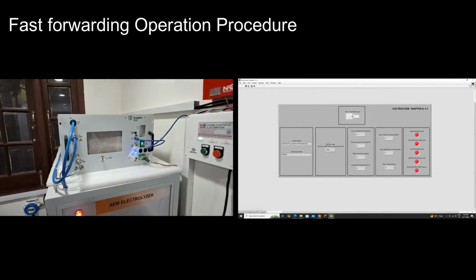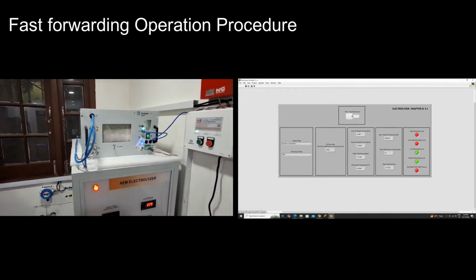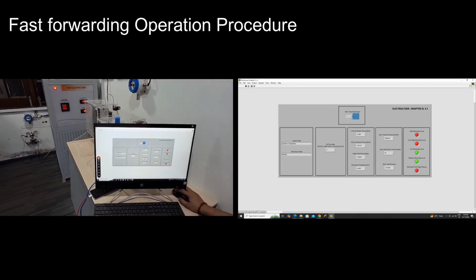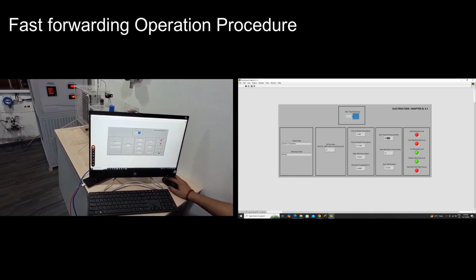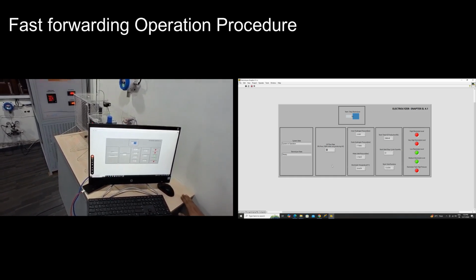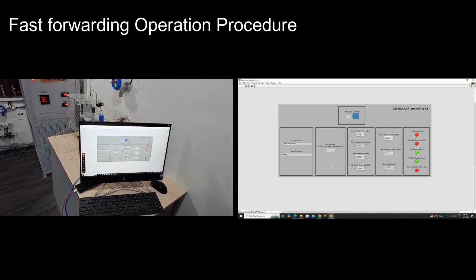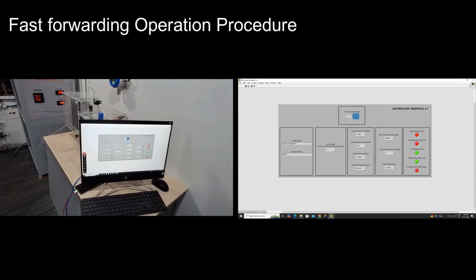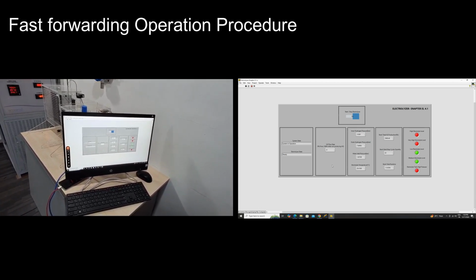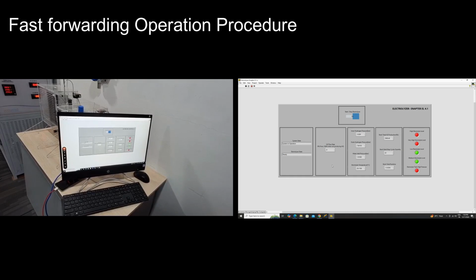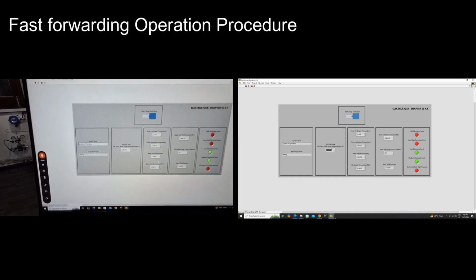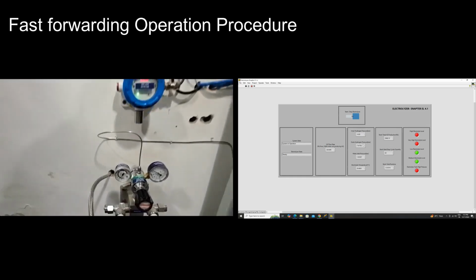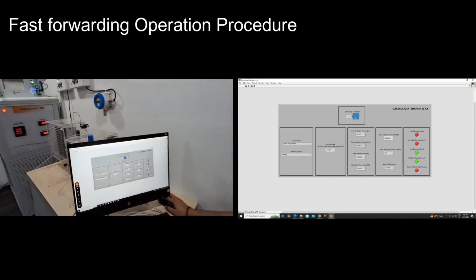As soon as we start the electrolyzer, it will move from idle state to steady state. It has already started, and you can see the production report here. It takes time to start the hydrogen flow. You can see the flow of hydrogen has started. We'll go up to 500, and the maximum pressure we can get is 35 bar. Now the system is operational. You can see the values here, the physical pressure meters also, and you can see the software also. You can see the flow increasing.